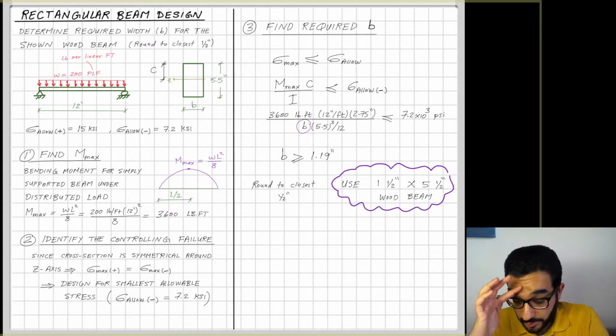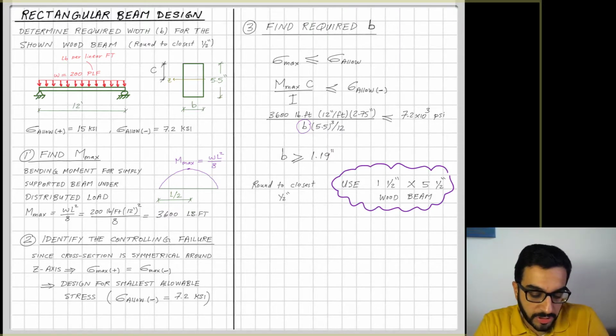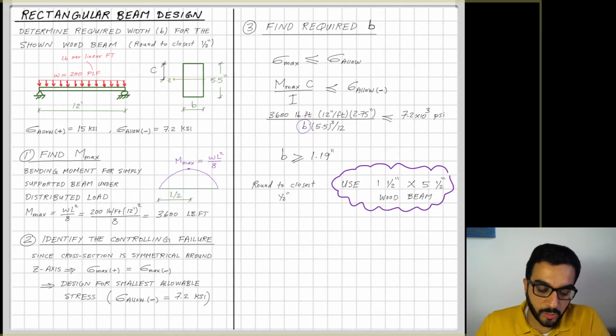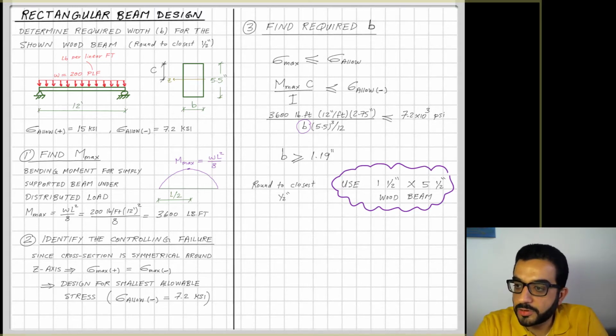So it's a simple example. Typically, we design the beams to figure out the widths, because the depths are kind of our goal, to maximize the depth of a beam always, and considering the space availability within a building or within a machine. So you always try to maximize the depth that resists the bending moment here.